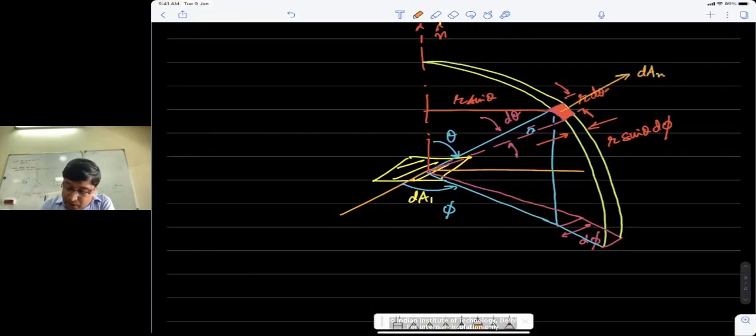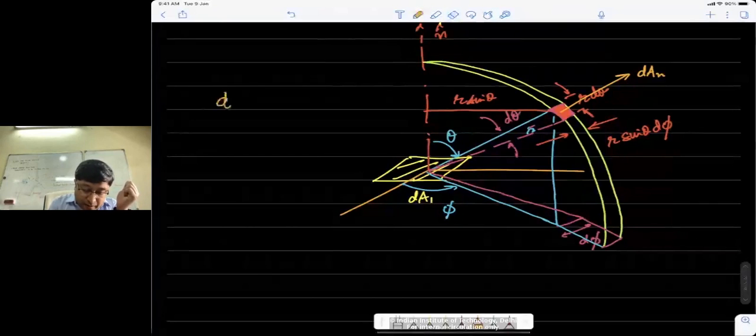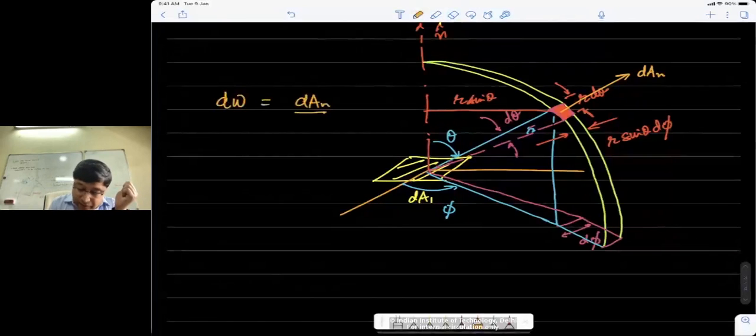So we're looking at this element, which is, let's say, at point dAn. When we talk about solid angle in the spherical system, we're talking about viewing this point dAn, which is on that slice at a distance r, but in the direction theta and phi. So we can talk about the solid angle d omega, which, as I said, is dAn, the area which we are viewing, versus the distance square from where we are viewing it.